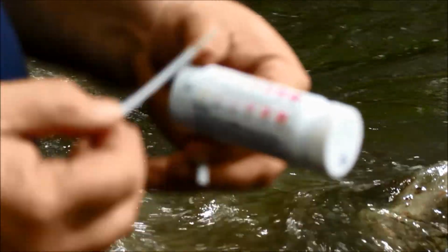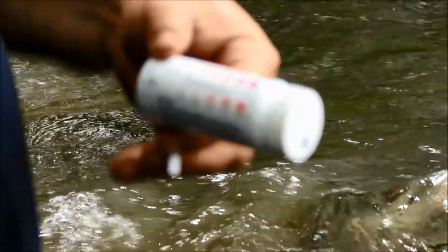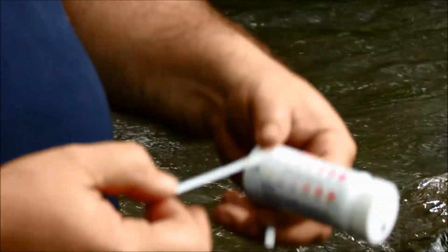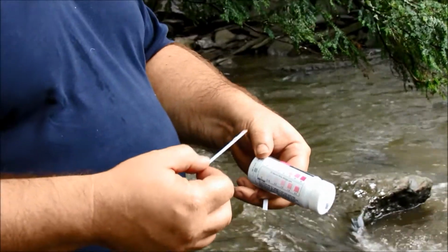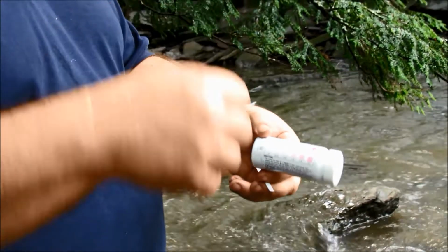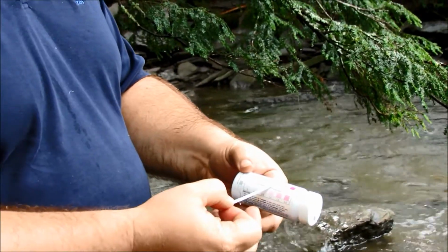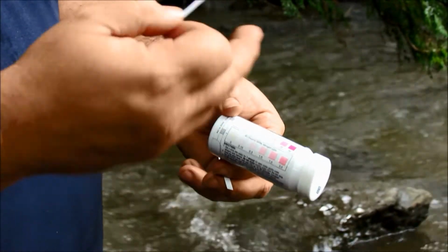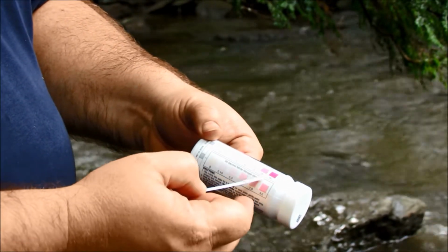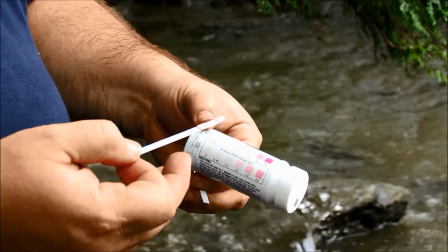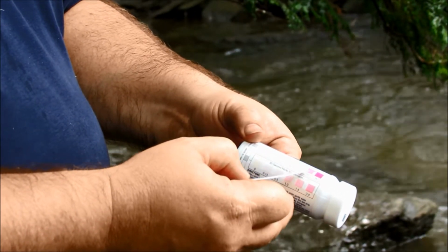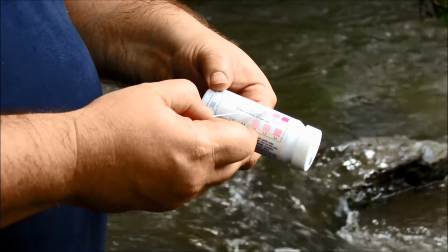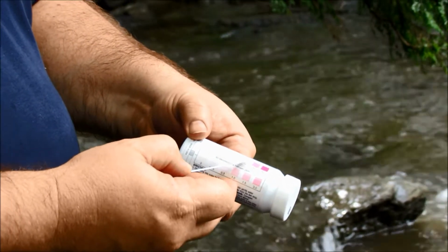As I mentioned before, if you're going to do some more homeowner type programs, or get more people to come to programs, offer a free water screening test. Have this laying around, let them dip their water sample and take a look. If the level's above 5, we usually recommend they get their nitrate tested. If it's above 10, that's a drinking water issue, primarily if they have infants, really little kids, because of blue baby syndrome.